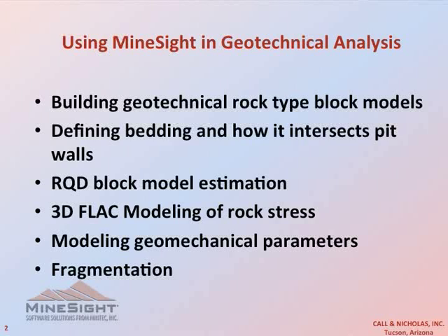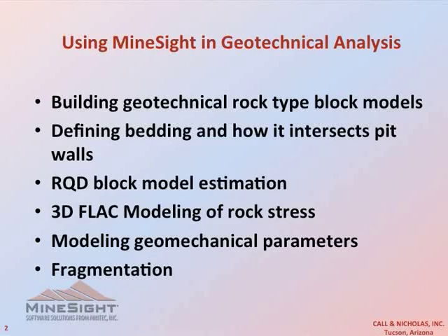3D FLAC modeling of rock stress. We use MineSight to code a FLAC model, which is a numerical modeling technique. Modeling geomechanical parameters. A lot of times RQD, which as long as everybody knows is rock quality designation, sometimes doesn't really describe what the rock is geotechnically. By using some of the other geomechanical parameters, we can then model and base everything on our analysis. And fragmentation. We're doing some things with block models and fragmentation that I wanted to talk about.